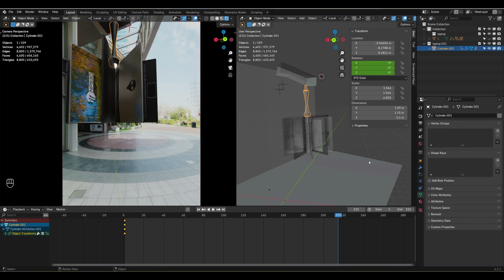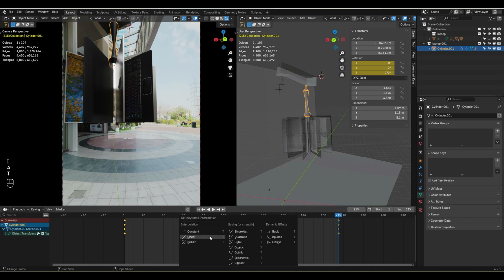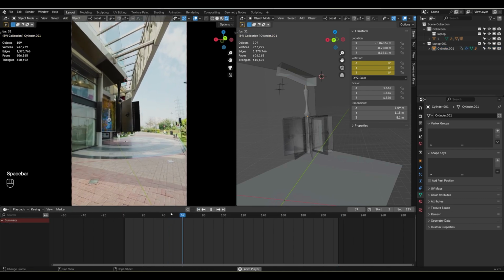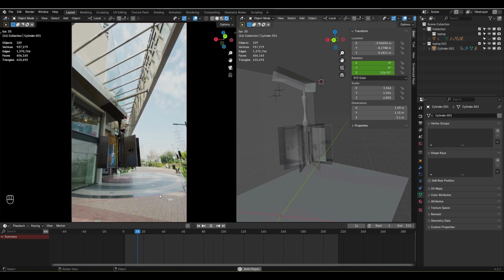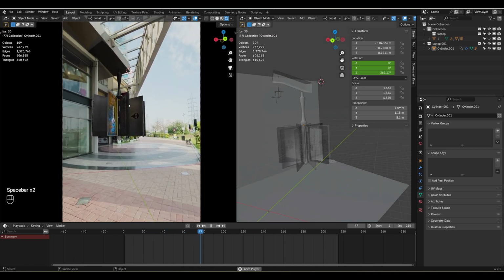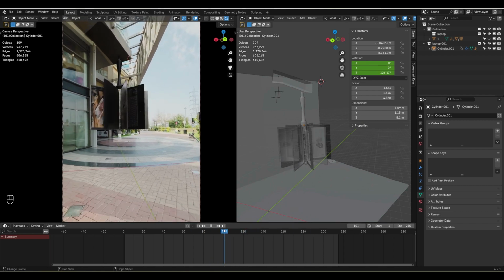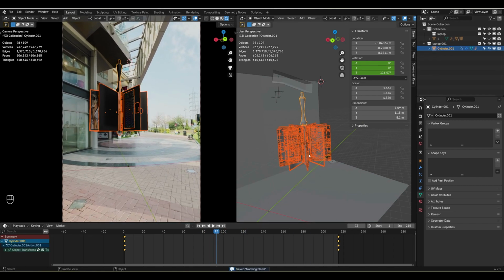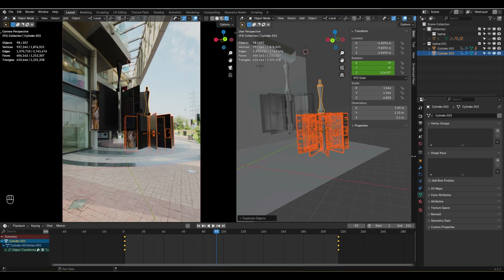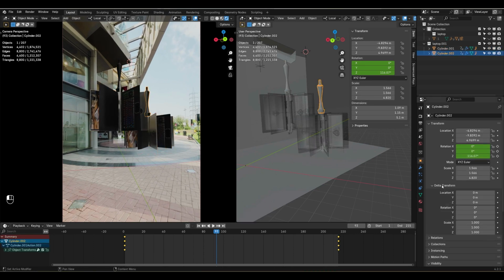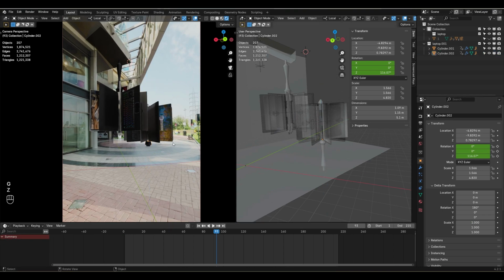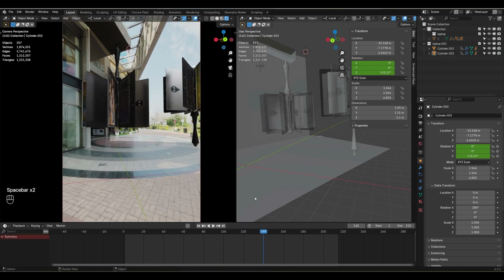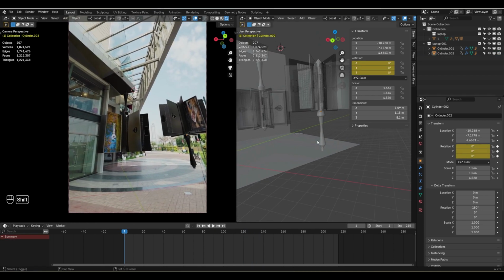Let's go to here and rotate this to something around 270, and let's press T and make it linear. And you can do a lot of stuff, just like select hierarchy, Shift D, and I can select this, go to the delta transform, and here I can control these things like 180 and just put it anywhere into the ground, and you will notice. Let me do something like this. This will look more crazy.